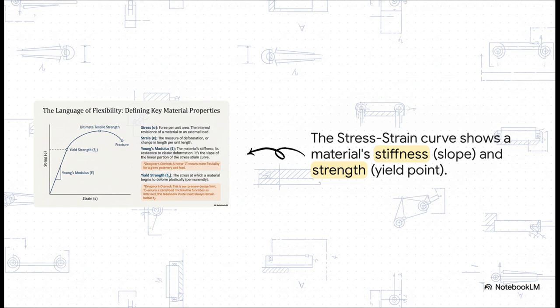That's the internal force the material is feeling. And across the bottom, on the horizontal axis, is strain. That's how much it's actually deforming. That initial straight line, that's our elastic region. The slope of that line is what we call Young's modulus, or E. And it's basically a measure of stiffness. The steeper that slope, the stiffer the material.